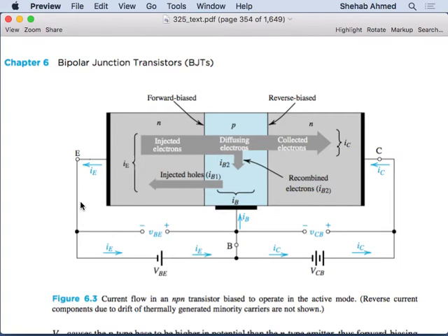But the value of the saturation current will differ in this case, because the saturation current depended on the area, the dimensions that we had in the circuit, and on the amount of charge that is diffusing and staying between these p-n junctions. But here we made it small. Small meaning we also have a small amount of acceptors. So the current diffusing from my base to the emitter is small as well, right?